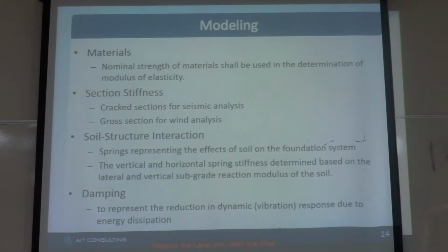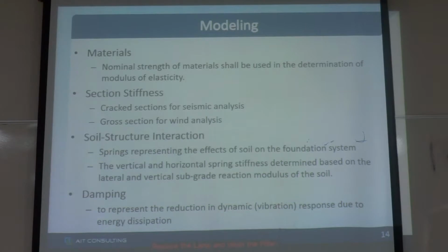If you have basement walls, you have to model the horizontal soil springs to consider the restraining effect of the soil. These spring properties can be calculated based on the substrate modulus of the soil from the geotechnical investigation reports.